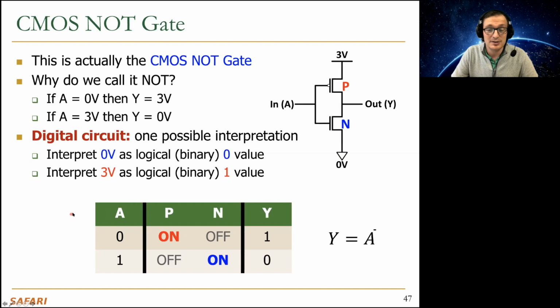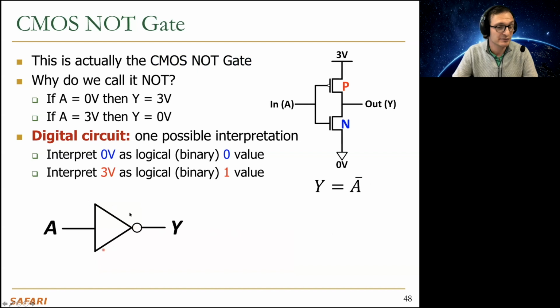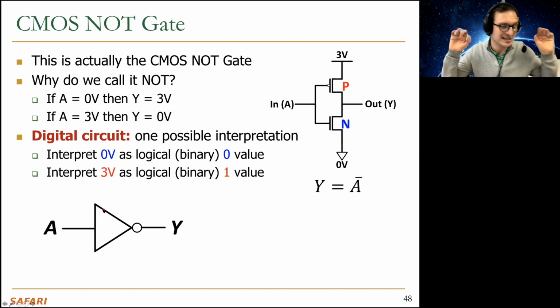Okay, so this is our NOT gate. Y equals A bar, complement of A. And we actually represent it this way. This is an inverter. This is the representation of an inverter. And whenever we have inversion, as I said, you always have this bubble in our digital logic representation. And in fact, if you remove this bubble, this becomes a buffer. So if you just have this triangle over here, if you don't have the bubble, that means Y equals A. Make sense? And it may actually enable amplification of the voltage over here. So there may be a good meaning for that, actually.